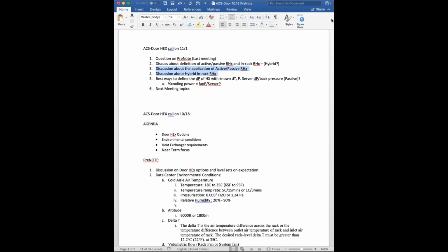And then what you would normally regard as wastewater, that then is going to the chip. So it would be warm water by the time it's actually touching the processors, but that's still sufficient to cool. And then really from there, it would be hot water, and then it would be going back to the data center. So in that case, from what they were looking to accomplish, they wanted really 100% heat capture. They wanted high TDP processors working within their supercomputer, but also having really a zero footprint in their existing data center. So that's why they wanted a rear door to neutralize the heat temperature.